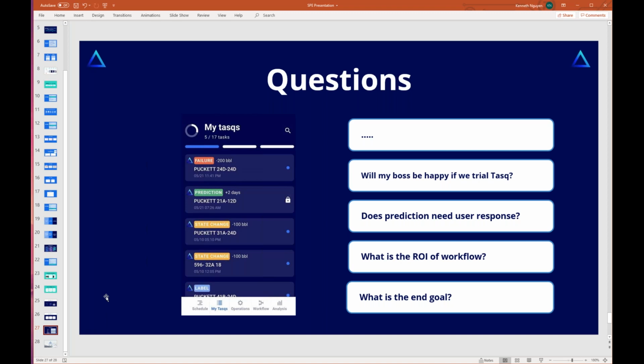Now, with regards to remaining operating time, that does depend a lot on the data set, right? So if you have a good sample of time to failure, then from that you can derive these time to failure or remaining operating time probabilistic curves that give you an idea of, for this particular well in this particular state, how much time do I have left to operate?